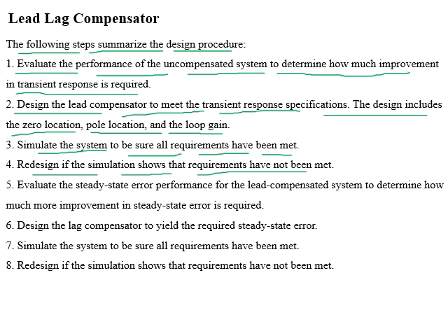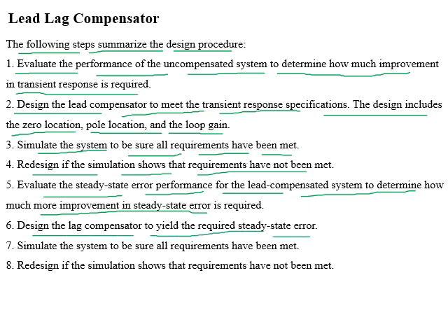We will evaluate the steady state error performance for lead compensator system to determine how much more improvement in the steady state error is required. After this, we will design the lag compensator for improvement in the steady state error. Then we will simulate to make sure that all requirements have been met. And we will redesign if required.